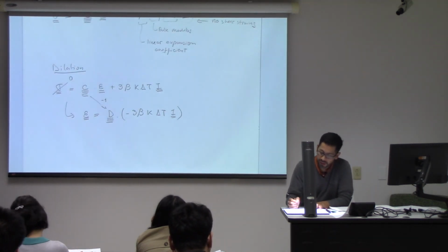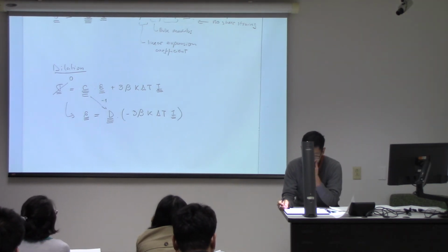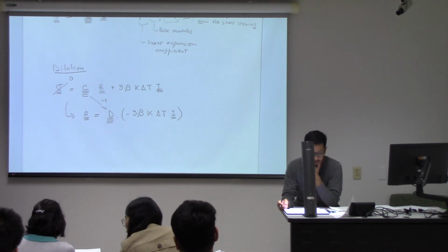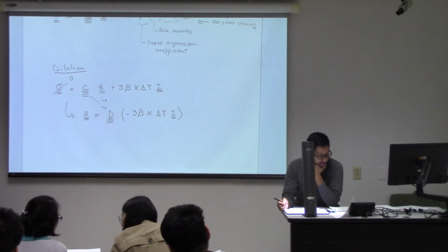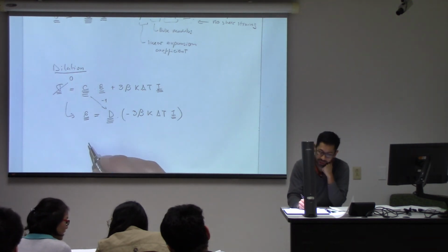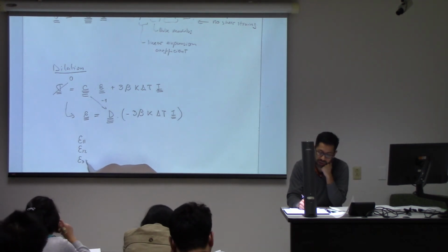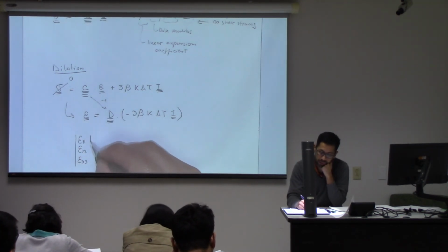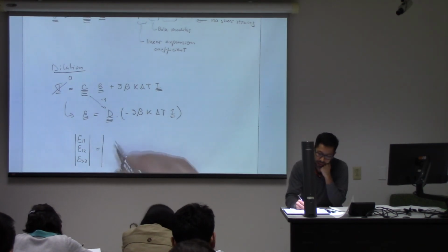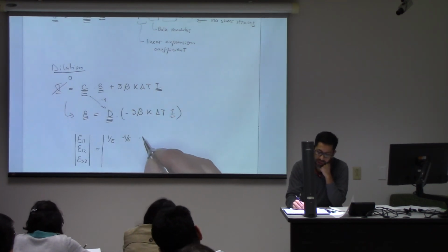And since I know that I'm not going to cause any shear strains, I can just look at the normal or volumetric strains. So epsilon 11, epsilon 22, epsilon 33, which is just the top of the strain vector, is going to be equal. If you remember, D is, I'm making an assumption here that you could make different if you wanted.